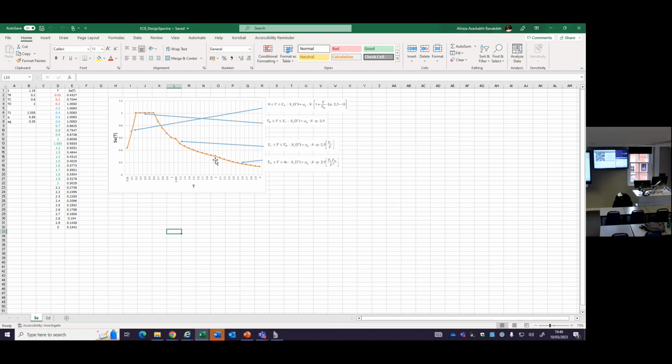So this is Eurocode 8: if you want to load your structure for seismic loads, you simply need to calculate the natural frequency of your structure. This is your coursework, again, I emphasize. Then you come here, get your number, multiply by the mass, and you have your design force, and you analyze your structure based on the design force. You get your internal forces, analyze simply, either by ETABS or by hand calculation, and you can design your structure and check whether it is safe or not. This is the whole picture of Eurocode 8.